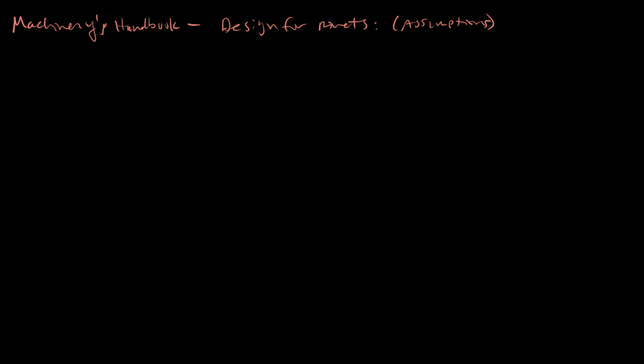And they are that, number one, the load is carried equally by the rivets. And obviously we know this is an assumption because if you don't have exactly the same friction, or you have offset load or whatever, you can have a pretty complex loading situation. So this is an assumption to simplify the analysis.